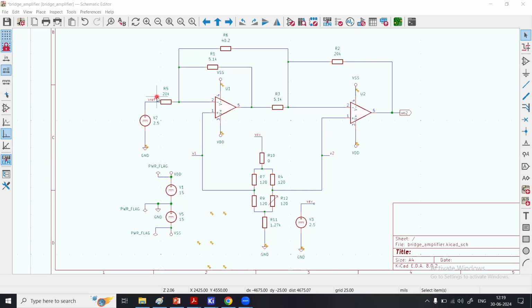For example, you must have heard about a strain gauge. A strain gauge is a sensor which experiences a change in strain when an external force is applied upon it, and in response to that it changes the resistance of its material. So when there is an external force applied to the strain gauge, it responds to that force as a change in its nominal resistance. And how to read that resistance change and convert it into an equivalent voltage, that is the topic of today's discussion.